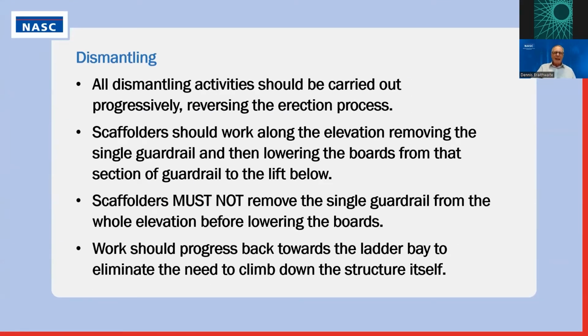Dismantling, it's basically a case of reversing the erection process. Scaffolders work along the elevation, removing the single guardrail and then lowering the boards from that section. They must not remove the guardrail and then start removing the boards. As I say, it's done progressively along. So the scaffolders work back towards the ladder bay, so they can climb down the ladder safely, and then continue on the next lift.